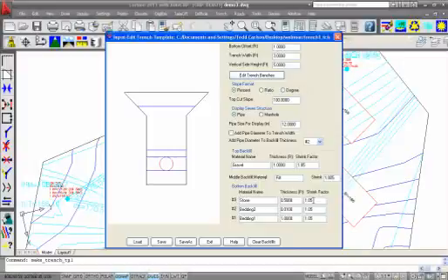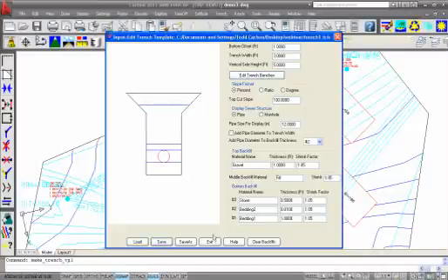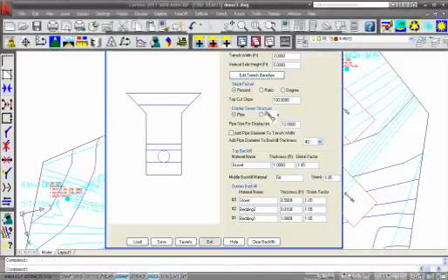Yep. And something else that we've added new to 2011 is that, for our cut and fill volumes, we've always had a shrink and swell factor, and that's something that we've added here for the backfill quantities. So this is a multiplier. 1.05 would be, the shrink factor would be 5% on this. Let me save and exit.